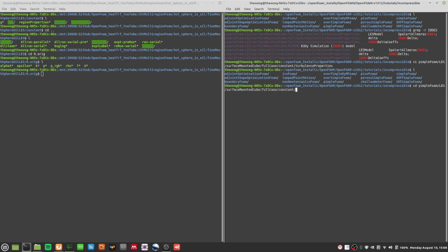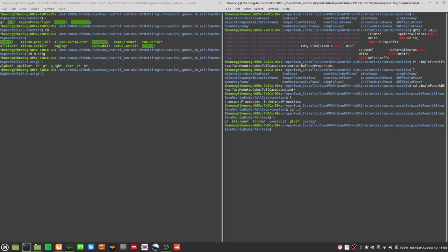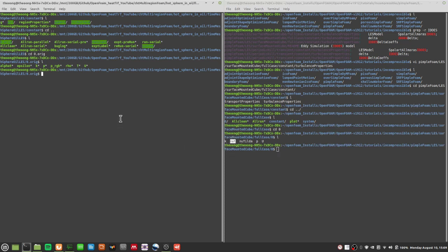Okay, so I'm going to cd here, and okay, let's go to the 0 directory to see what we need. Okay, so we have nu T. Alright, nu T is the main thing you'll need there. That's the turbulence itself. k is the turbulent kinetic energy. But we also need an omega field. So there are a number of fields to add. Why am I adding all of them? Okay, nu T stands for turbulent viscosity.